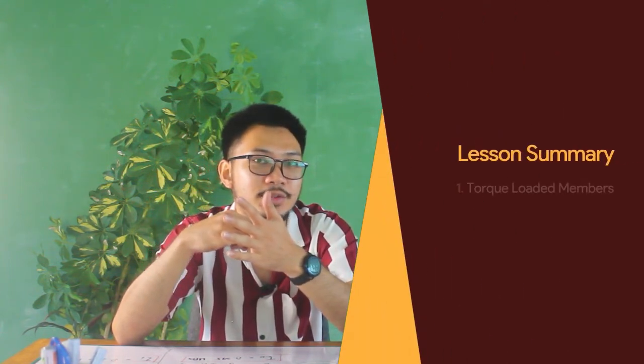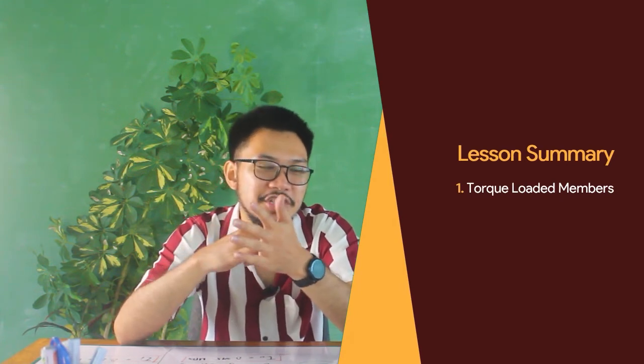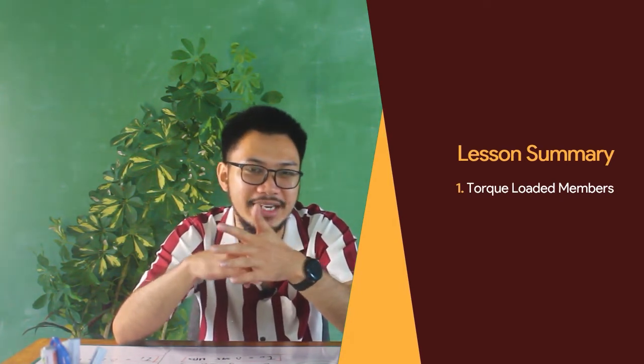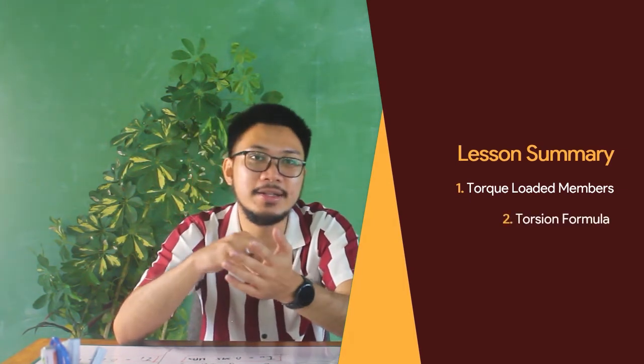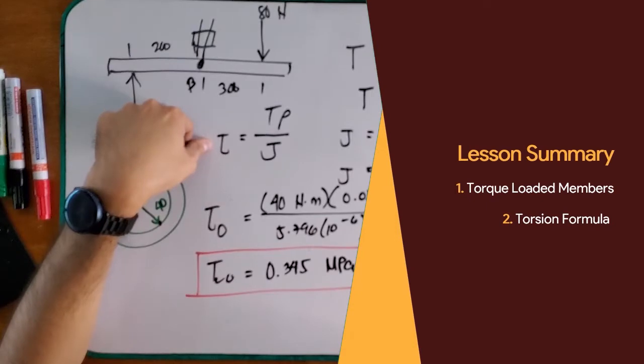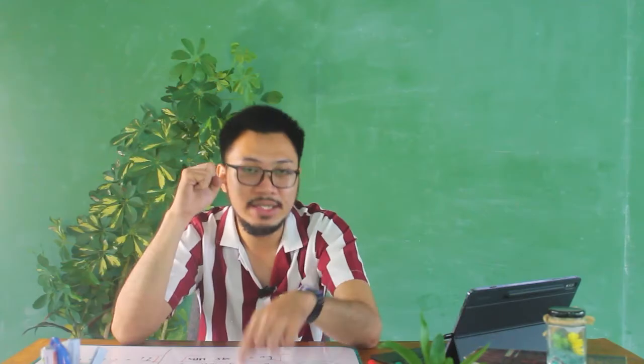So as a summary for this lesson, you already know what torque-loaded members are and the relationships of shear stress and shear strain. We also have generated the torsion formula, which is your tau max is equal to TC over J, or your tau is equal to T rho over J. And then lastly, you were able to solve problems in relation to your torque and your shear stresses.